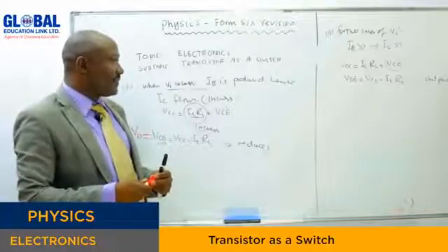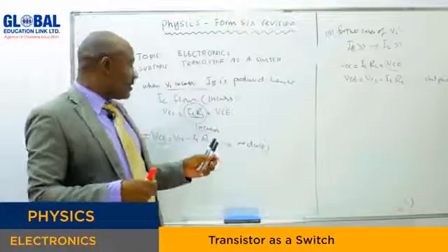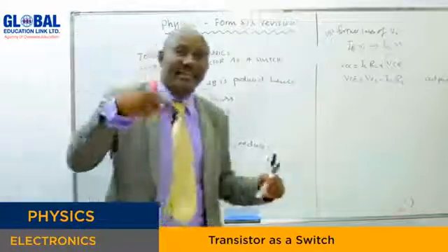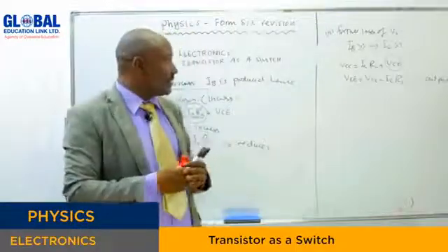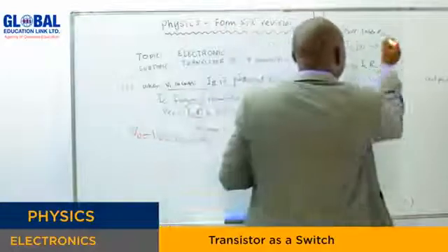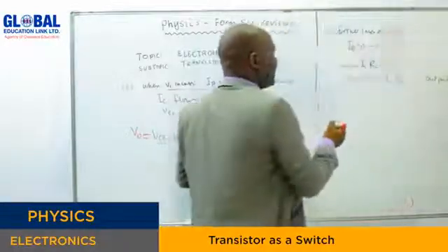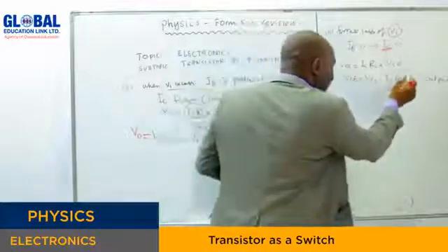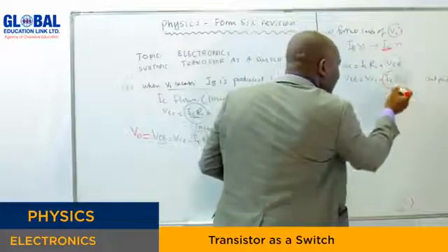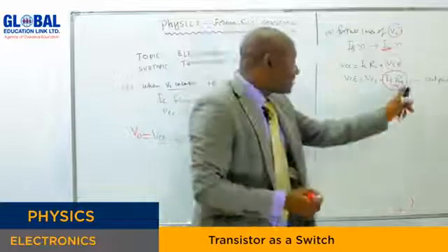We have the small voltage range. We remember, when talking of a transistor, the output produced cannot be greater than the supply voltage. There's a limit to the output that can be produced. So when the input voltage increases, it makes this current increase, and it makes these values increase. This has a limit.